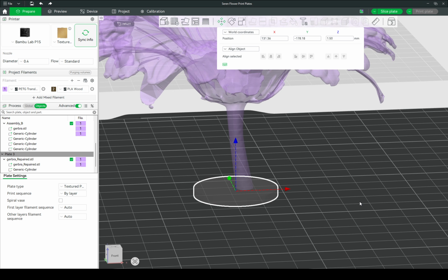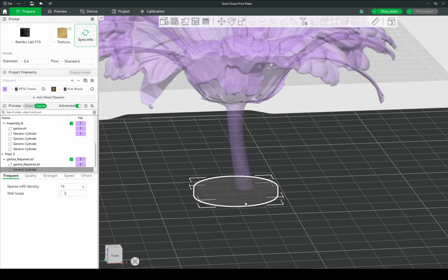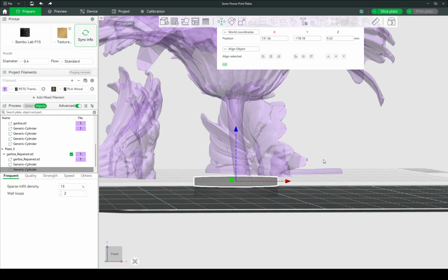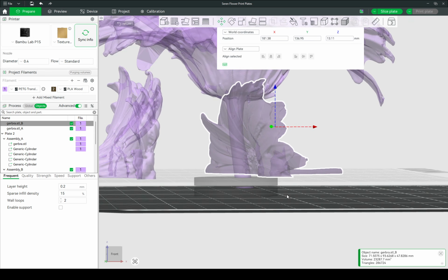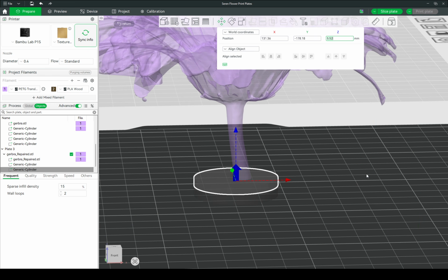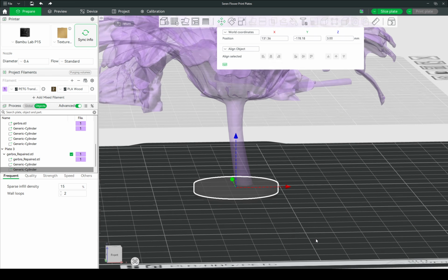just to get it on that print plate. And from here, I'm going to take that same cylinder shape, copy it and paste it. You'll notice another cylinder's come over here, so I can move that. It's an exact copy of its friend here, so I'm going to just use numerical control to get it exact. So I'll get the second disc. I'll put that, if it's 3 millimeters thick, it should be there like that.